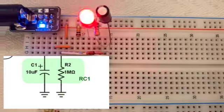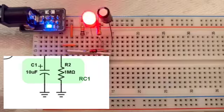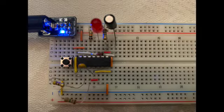RC1 controls on how long the clock will keep on going. The more capacitance and resistor there is, the longer the clock signal will go. The clock will keep on going until the capacitor empties.